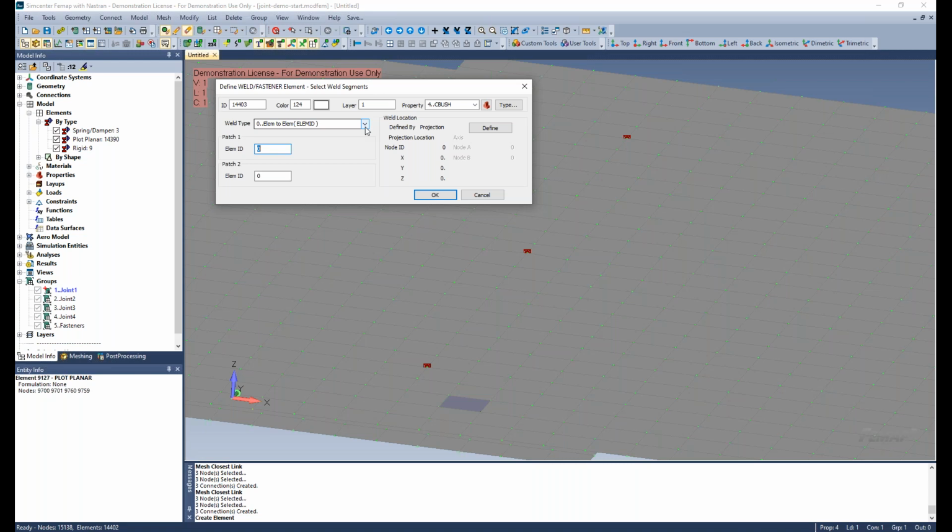We want to stick to fasteners as much as possible. CFAST. You can see these are the options, but some of these options only really apply to the spot weld. It's really only the last two that we can use. So now I'm going to start connecting elements together, and it also wants to know where the fastener should be in space, which could just be an XYZ location, or I can pick it based on a node.